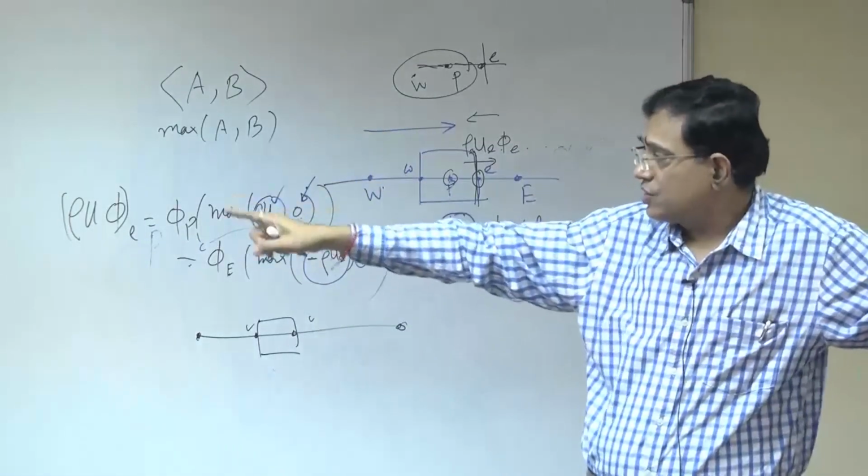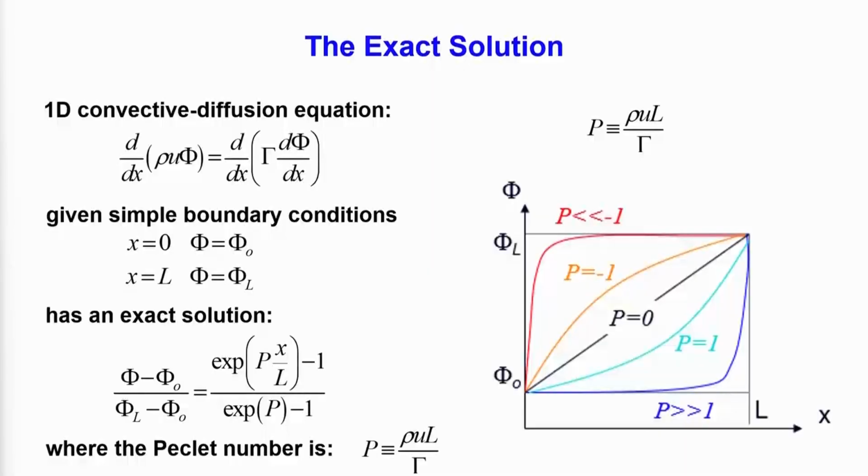So, you can see that if the Peclet number is 0, then it is like the central difference scheme, that is linear. That means for low Peclet number it is fine, and if the Peclet number is large, much less than -1 or much greater than 1, in both cases the magnitude is large, and it nicely reproduces the upwind scheme, like a constant. But if it is in between, then there are ways of representing this exponential function by some low-cost function. Low cost means computationally low cost.